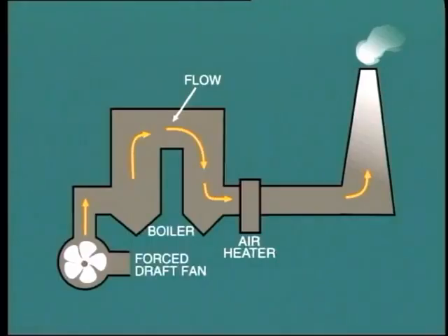We'll be looking at the actual measurement of draft in the furnace and throughout the boiler later in this program when we discuss boiler operation. One way to prevent the problem of gas leakage from the boiler is to maintain the furnace and gas passages under a slight negative pressure.